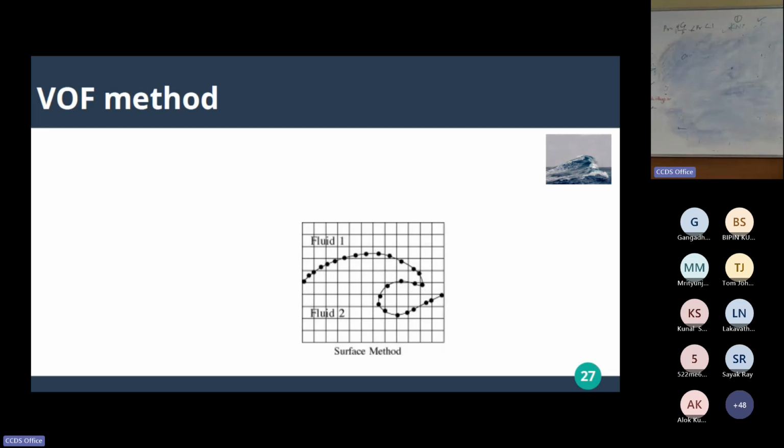You will have phases, liquid, air, and also marker points, which you advect. But that's a bit of a challenging task, though it captures your interfaces. Without capturing interfaces, you can't transport stress terms from one phase to the other phase. Unless these stress terms are properly modeled, you don't really simulate the correct picture. Heat transport, at that boundary, the stress terms are the ones responsible for any evaporation, any condensation, any breakup, or any chemistry that happens. The interface has to be really resolved.